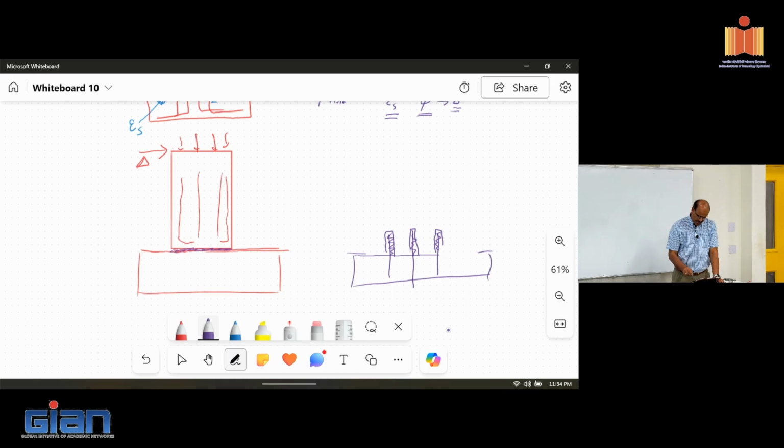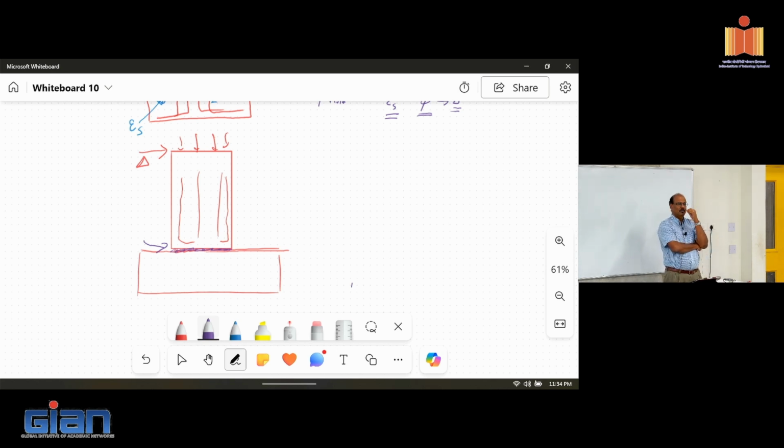So as you would imagine, let's say we have enough shear resistance, then you would develop a crack at the interface, right? You all agree? That's an obvious location to develop a crack. So the concept of a jointed wall is basically to say, no matter what we do, it's going to develop a crack at the interface where the two elements are getting connected. Therefore, we should acknowledge and take advantage of it. If I allow this crack to develop, you basically have some vertical load, so some pre-compression. And initially it's going to start behaving like that.